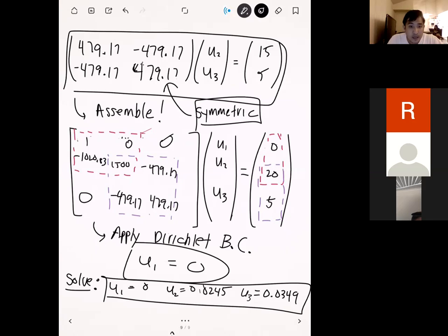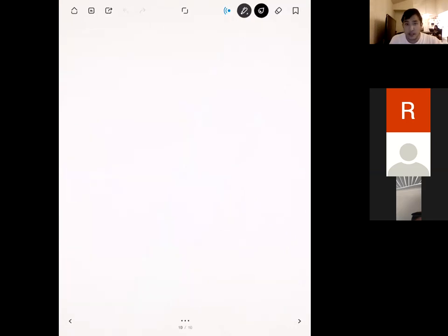The other thing is, just because we're getting these matrices in a different way, don't forget to apply your boundary conditions. It's a little easier to miss them in this case because we're going to be doing a lot more math than usual. But don't miss your Neumann boundary conditions and don't miss your Dirichlet boundary conditions either. Make sure you have those accounted for before you hit solve in MATLAB. Okay, so that's the basics of the process.